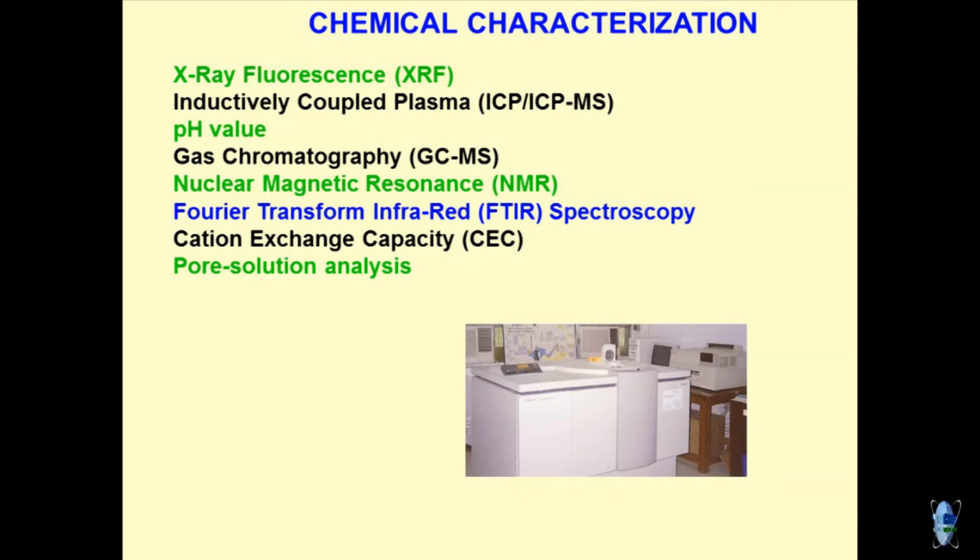So, what ICP units are? They are used for determining the level of contamination of chemicals present in the solution of any geomaterial. So, you take geomaterial, dissolve it in water, make a solution, let the chemicals or heavy metals which are present in the system leach out in the solution, and then you analyze the solution to get the concentration of heavy metals which are present.